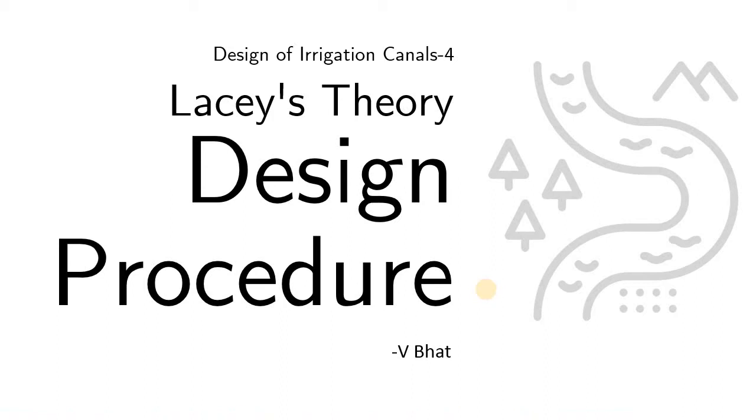In the fourth segment of design of irrigation canals, we shall be looking into the design procedures adopted in Lacey's theory. Before that, Lacey argued that the sediment is kept in suspension not only by the vertical component of eddies which are generated on the channel bed, but also by the eddies generated on the sides of the channel.